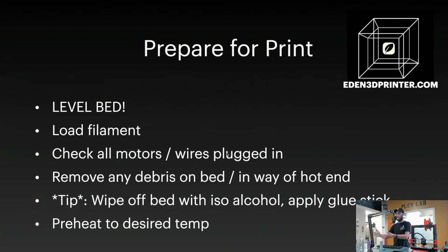You'll have a print fail, slide off the bed. It might wobble, and you'll have a spaghetti mess in 20 minutes or half an hour when you come back. And yeah, it's a problem. It's really nice to keep the bed very level.